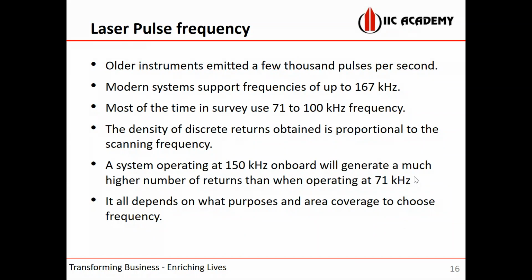That's why most of the time during surveys we use 71 to 100 kilohertz frequency. With 71 kilohertz or less, the penetration range will be more, and you will get less information. If you use more kilohertz, you will get more data and more information, but less penetration. This technology we use for different height measurement, penetration methods, and elevation evaluation methods.